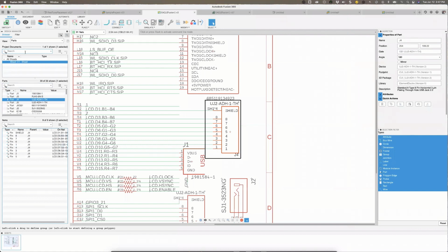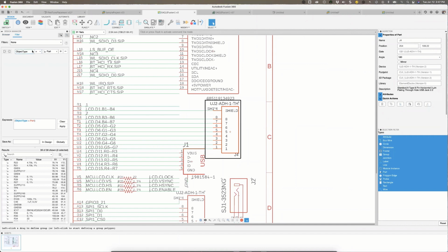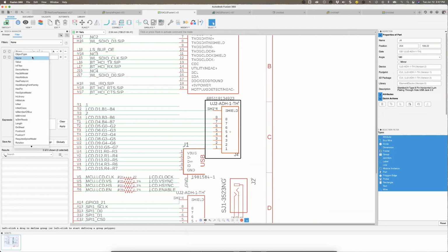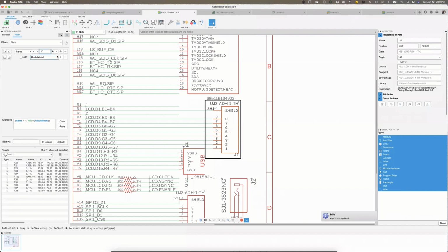It's very convenient. Now you could create filters as well. So if I go to filters, I could tell it, I'm going to look for all the components that have the letter R, and I want all of the components that have a 3D model as well. So I say apply. Oh, I got to put an asterisk there. Sorry. R for resistor, asterisk, and they have 3D models. And it gave me a listing of all of the components that have the letter R, which are the resistors, and they have a 3D model assigned to them.